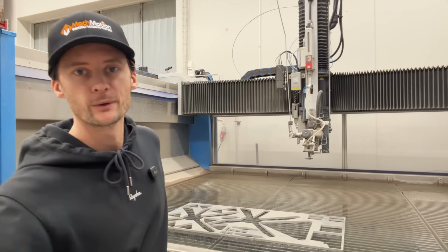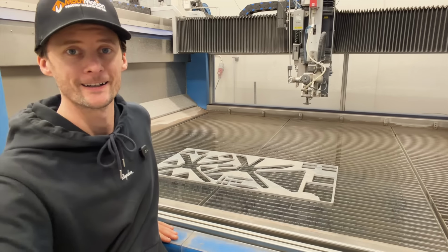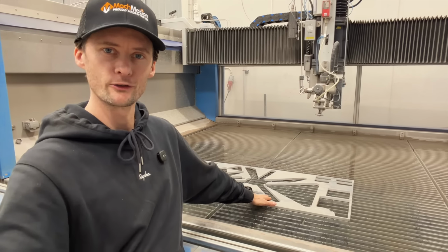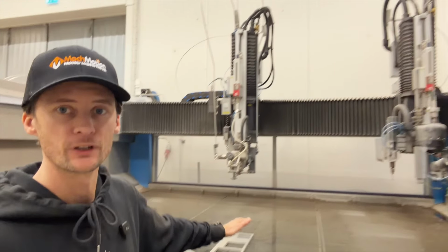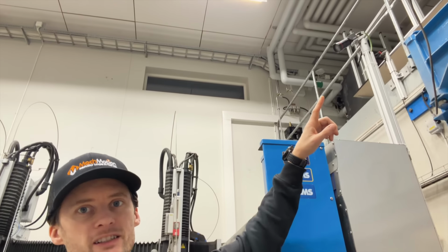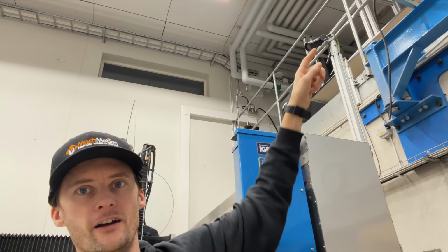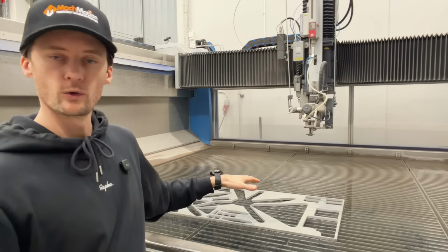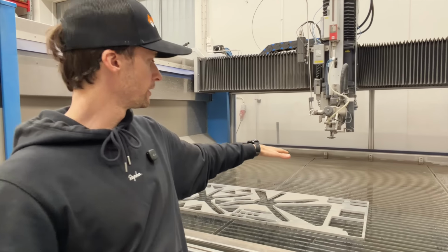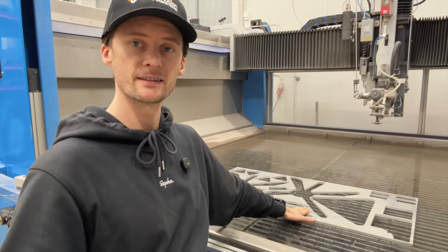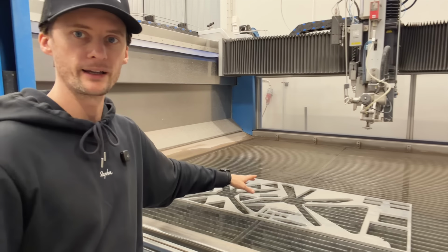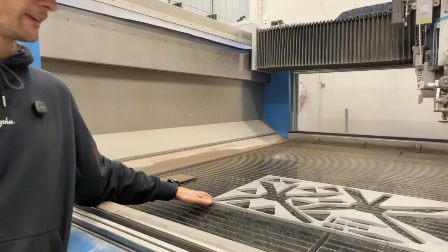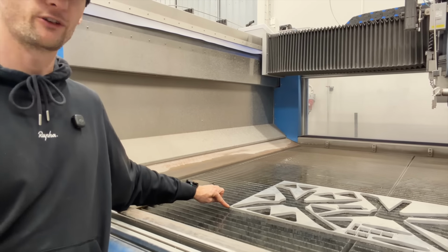All right, guys, I only have one more feature to show you, and it's another camera. It's one for part placement. You photograph your machine table, and you do that with a GigE camera, which is a standard protocol for industrial cameras. You will get a bird's view, like a top view image, of this imported into our CAD/CAM. So we can place parts on here, and then right here, we can set our 0 point, so we know that we are going to start from here.